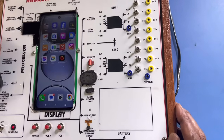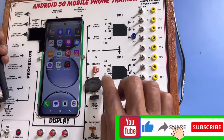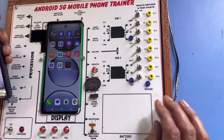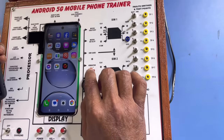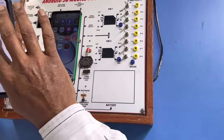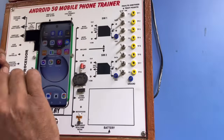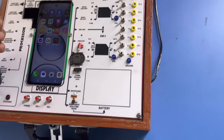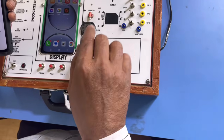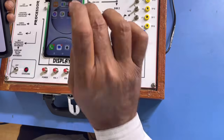Now we shall see the testing of different sections of the mobile phone. First we shall see the working of the vibration motor, then the speaker, and then the working of the microphone. Switch the vibrating motor on and off here. Now I am making a phone call to the 5G mobile. See, this vibrating motor is rotating and sound is produced simultaneously. This is just testing of the tone and this vibration.